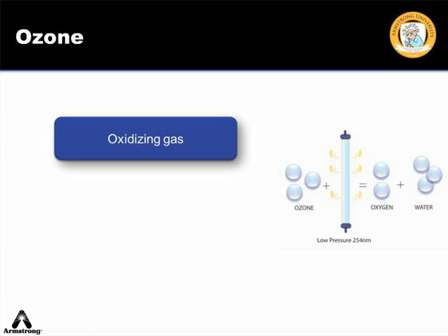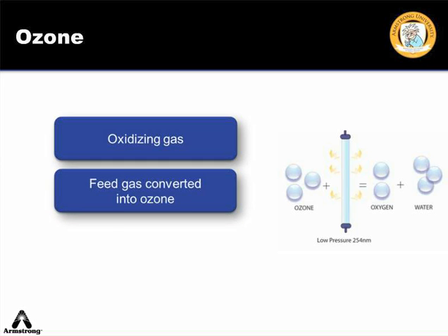Ozone is a strong oxidizing gas formed by the combination of three oxygen molecules, usually by controlled electrical discharge across a dielectric barrier using air or, for improved efficiency, oxygen feed gas, which has been preconditioned to remove impurities and traces of water. The result is that a proportion of the feed gas is converted into ozone. For large industrial ozone plants, using oxygen feed gas, the conversion may be greater than 10%. Typically, for air-supplied ozone generators, the conversion rate is 3% and 6% for oxygen-fed units.